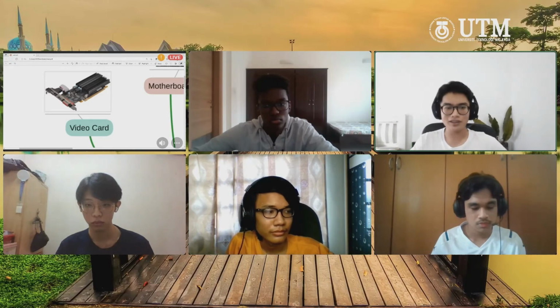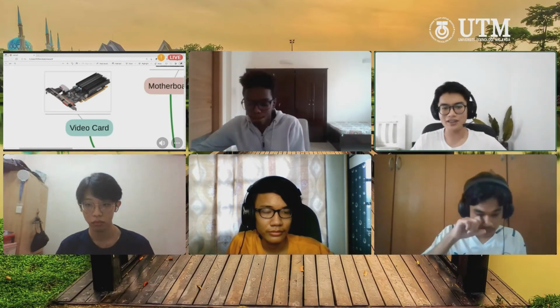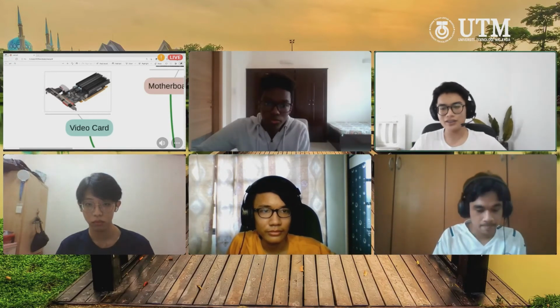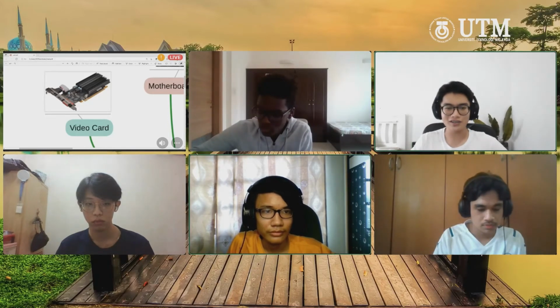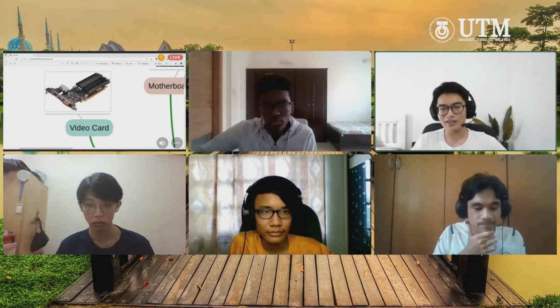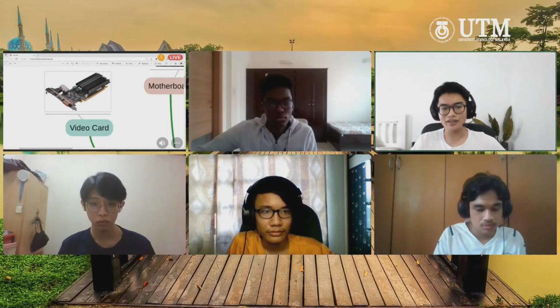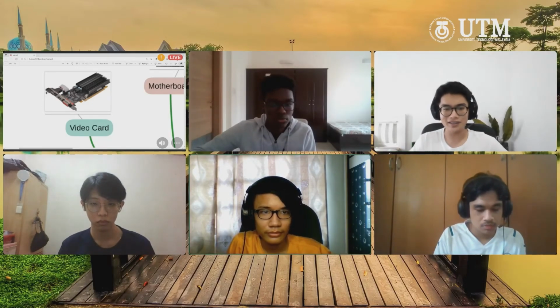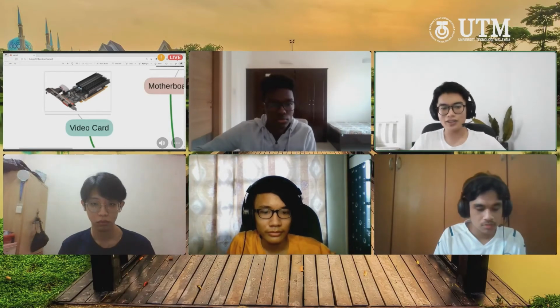Then push down gently on the slot connector and ensure to secure the lock clips into place. Then screw the rear panel back and secure the card into the chassis. Then connect any required PSU cables,